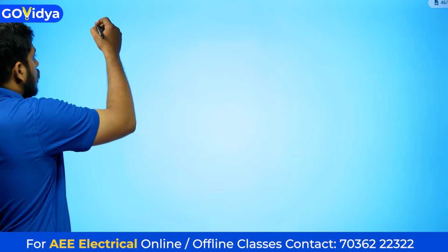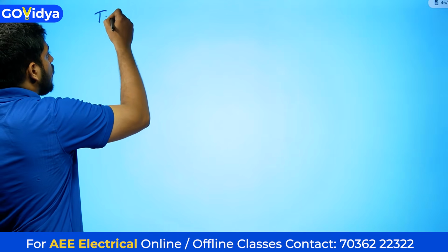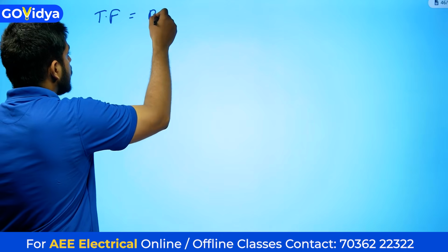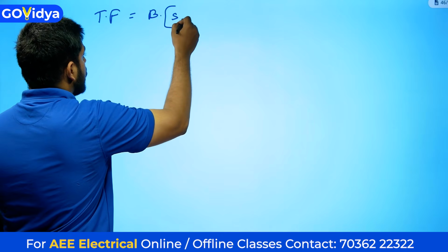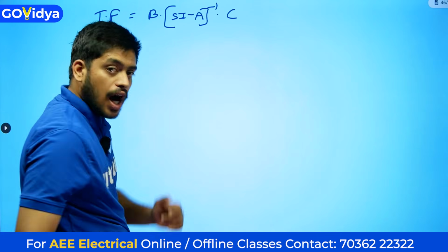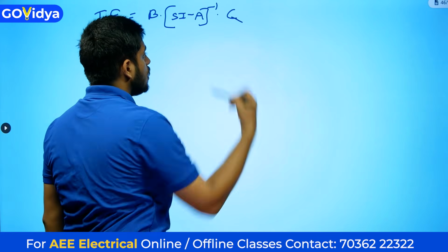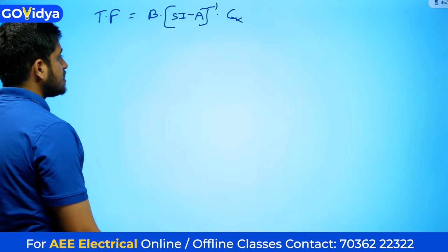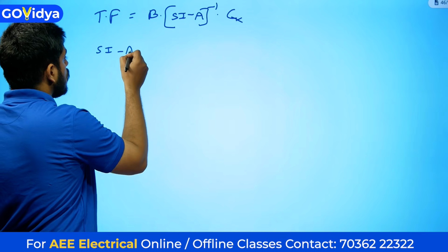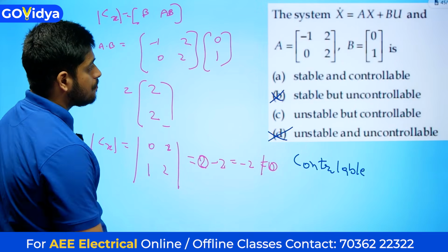So what is the equation to find the transfer function for these types of state models? C into SI minus A whole inverse into B. However, C is not given, so we will eliminate that. We need SI minus A whole inverse. First let us find SI minus A. What is the value of SI minus A?